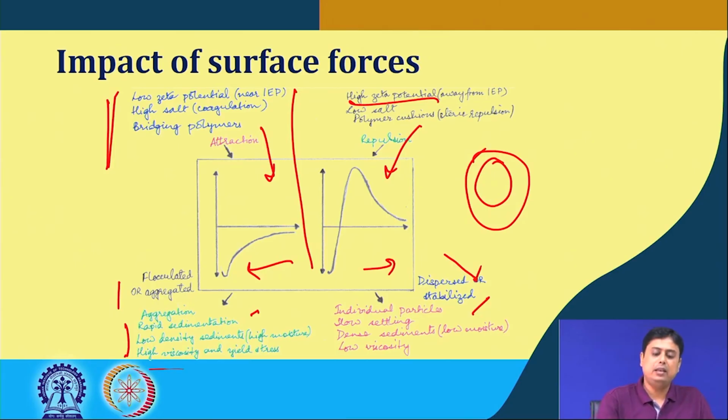So, that results in individual particles, low settling rate, dense sedimentation or low moisture content, and low viscosity suspension or material. So, this is how the solution property can control the attractive or repulsive nature of the force, and how this attractive and repulsive force is then translated into the solution behavior, the suspension behavior, or the fine particle behavior.